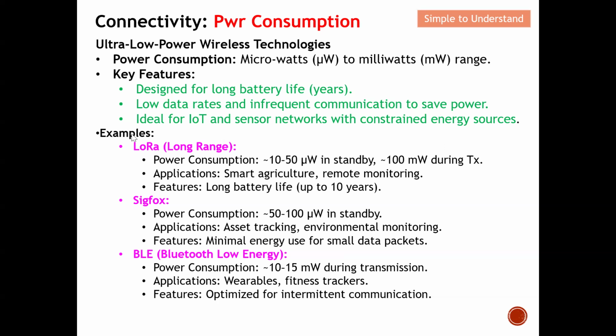Some of the key examples for this ultra low power wireless technology will be LoRa. You can see that LoRa's power consumption is maybe a maximum of 50 microwatt in standby. When it transmits, it only uses about 100 milliwatt. The key applications for LoRa are not limited to these two, but in short, LoRa is a good implementation for agriculture and some forms of remote monitoring. The key feature is long battery life, up to 10 years, maybe up to 5 years. For me, I would say up to 5 years.